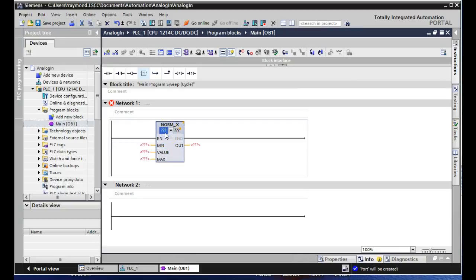Over on this side, we decide what type of numbers we are bringing in. So I'm going to come in from an A to D converter, and when we talk about A to D conversion, it's 1,023 counts, with no fractions or anything coming in on the left-hand side, right? So what type of number would that be? We have to go up to 16 bits, so we're going to use a double integer. So I'm inputting a double integer.